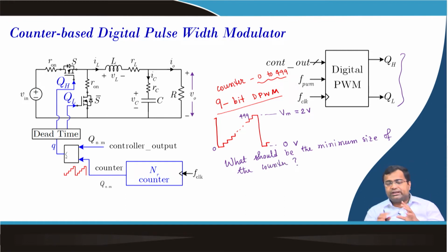So, first of all, we need a positive 2 volt, and the Q format we know, because it has to take the 9 bit totally. So, for the dot side, what will be M? That means we are talking about N dot M. First of all, we only need positive value. That means we must have a 0 MSB to represent the positive number. So, that means it should be 0 in the MSB side. Then the rest of the bit can be utilized to accommodate the number.